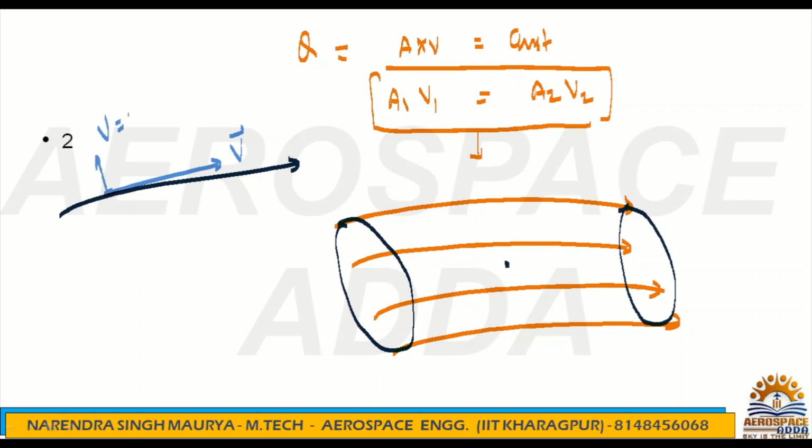So what is the velocity perpendicular to the streamline? Zero. There is no perpendicular. So basically, the normal component of the velocity over the streamline will be zero. Only the tangential component will have a value. Because tangent means only the tangential value will be there. There is no normal value, there is no perpendicular value. If there is no perpendicular velocity over the streamline, then obviously over the stream tube too. Suppose this is the surface of the stream tube. Perpendicular to it, there is no velocity actually.